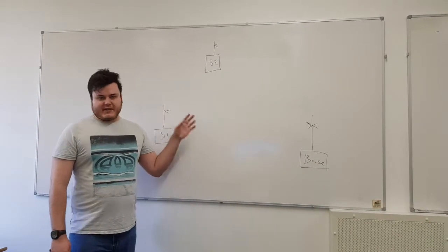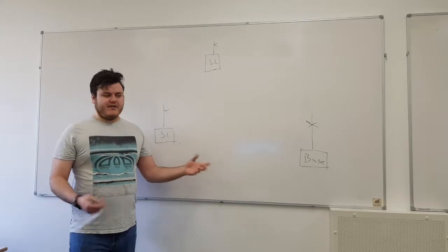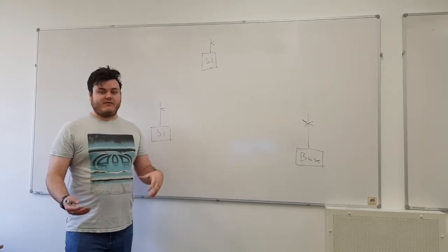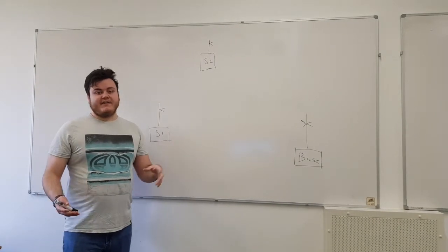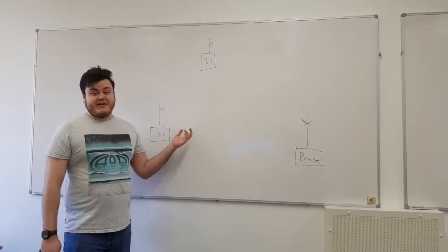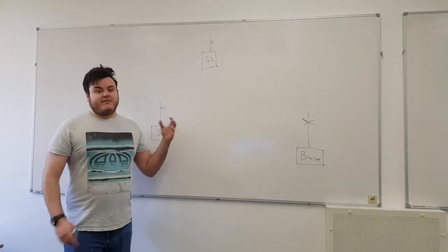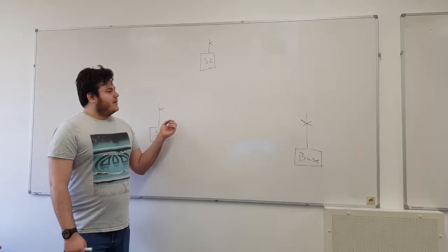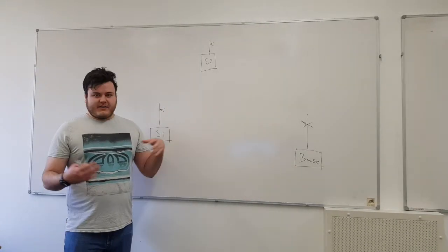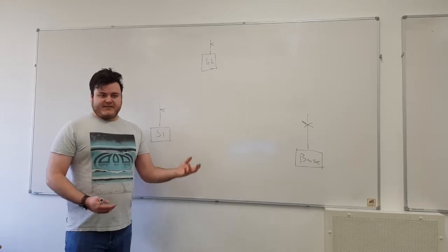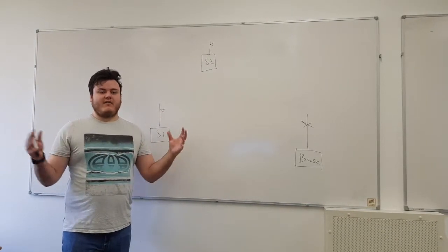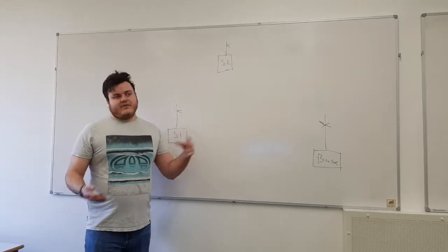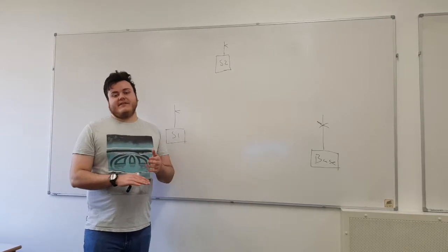The problem with some of the frequencies like Wi-Fi, which is very established and we could probably easily use, is that it's still quite low range because it uses a free license to access the radio frequency. It's limited to about 20 dB in transmission power, so that limits its range to approximately 100 meters or so in free airspace, but in more of an urban environment, probably only 30 meters or so. So to get around that, the option would be to pay for a license for the radio frequency and we can transmit a lot more power and get a lot more range out of whatever frequency we choose. Unfortunately, that is quite expensive and we want to keep the cost low on the system.